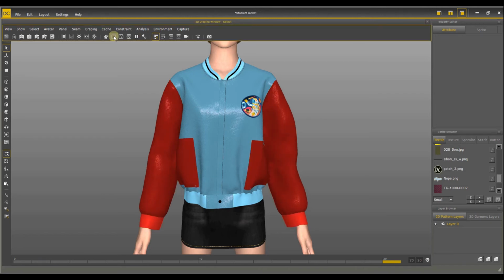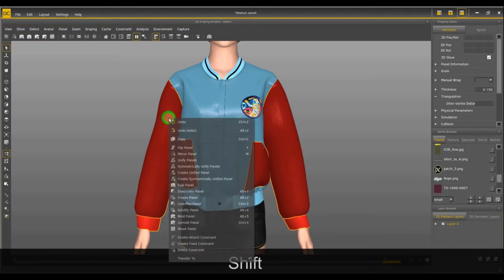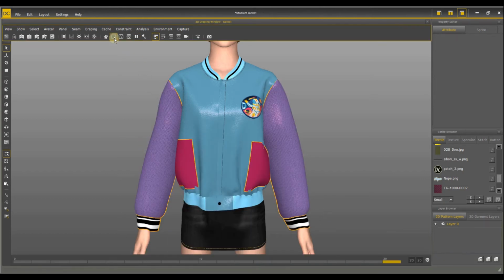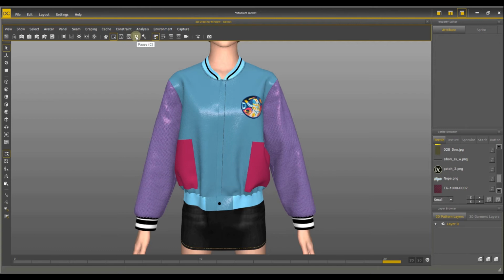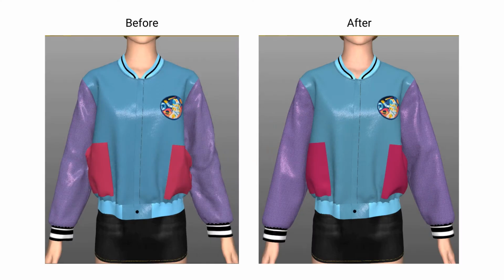At this time, after pressing static play, you can find that the panel is constantly being stretched. When the panel is stretched to a certain extent, press the pause button and change the panel mode to Stiffen Panel and rerun the static simulation. In this way, you can find that the original toggle panel problem has been solved.